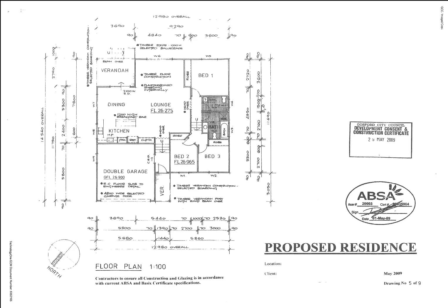If, for example, we were building a brick veneer building, we would have a brick skin, a cavity, and then we would have our internal framing. So we might have a dimension of something like 225 to 250 as the overall width of the external walls, whereas the internal walls would probably still show up as 90 or 70, depending on what's been chosen.